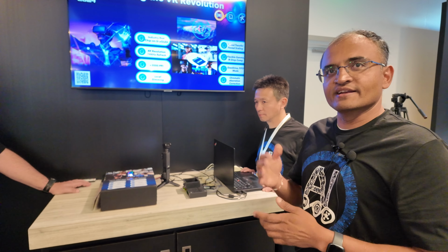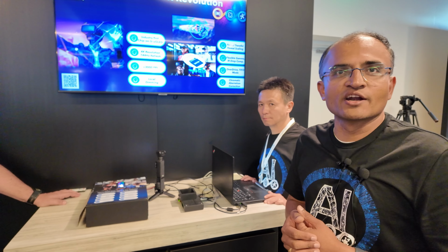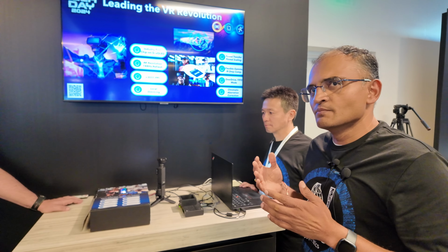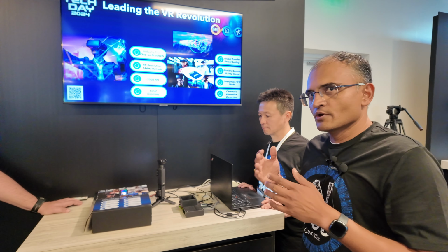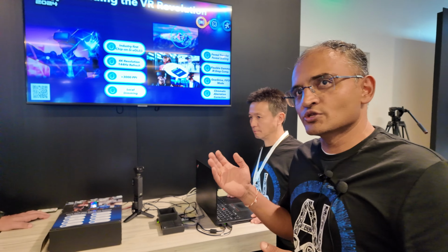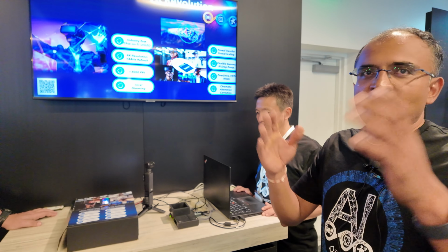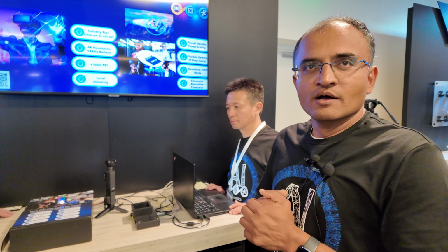For mobile applications like VR, where battery life is an important aspect, local dimming provides power savings by disabling the backlights that do not need to be on because of the black display. It reduces the motion blur as well, because you're getting better contrast, and you're getting the higher refresh rate, so you're getting more pixels through the pipeline. Now you can have a much broader field of view, which provides a more immersive experience.